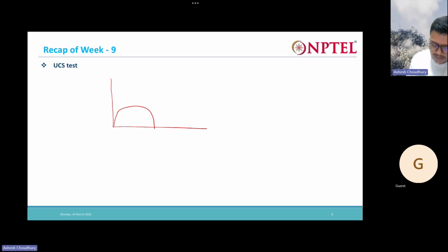So from here, what is this? This is called my C undrained. And this is sigma 1. So what is this one? This is sigma 1 by 2. So this sigma 3 is equal to 0. This is sigma 1, which can also be known as the Qu, the unconfined compressive strength. So my Cu is nothing but sigma 1 by 2, which is nothing but Qu by 2.